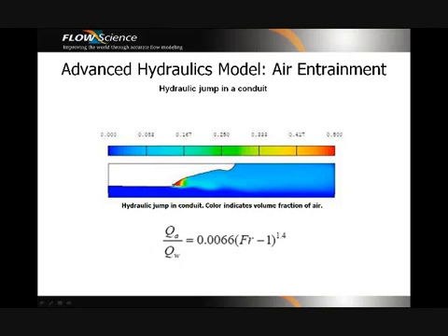This test case involves a closed conduit. The conduit is inclined with respect to the horizontal. The lower end of the conduit is immersed in water with a hydrostatic head above the top edge of the outlet. At the inlet, water enters with an assigned depth and rushes down the conduit under the action of gravity. A hydraulic jump develops about a third of the way down the stream from the inlet.